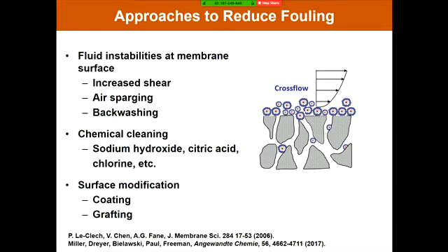And there's been a lot of effort in the literature to modify membrane surfaces to make them more fouling resistant, and many different approaches to this. There's still a lot that is unknown at a fundamental level. This is one of the focus areas of our Department of Energy Center, to better understand the hydration barrier at the surface of membranes in order to design more effective fouling strategies. However, it is widely believed in the field that one way to reduce fouling, particularly of hydrophobic foulants, is to increase the hydrophilicity of membrane surfaces. That's one of the design rules that is widely practiced.